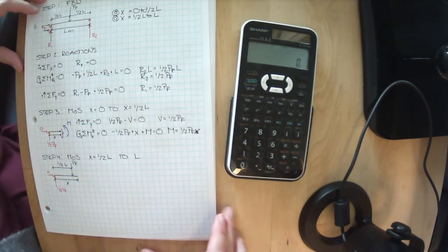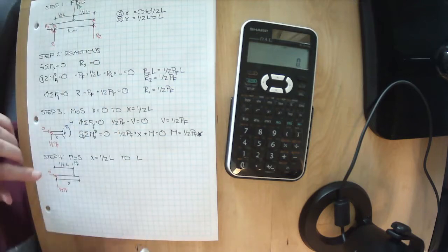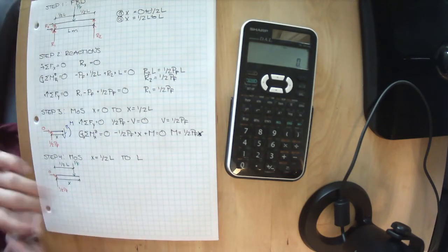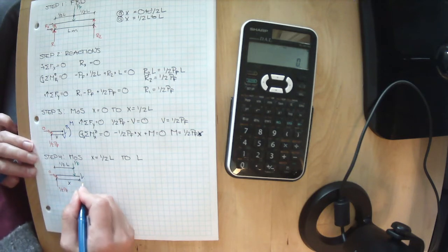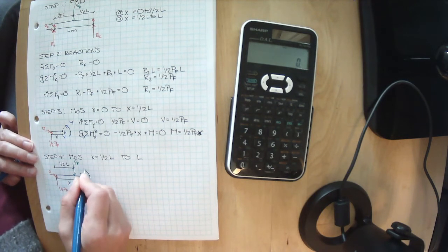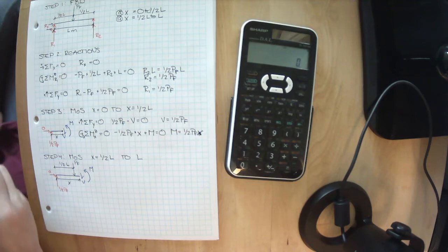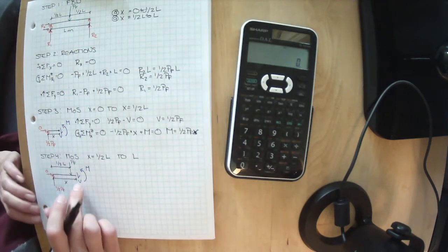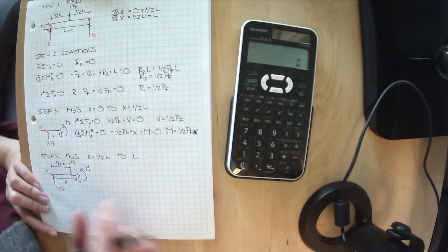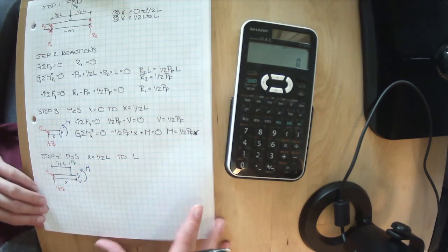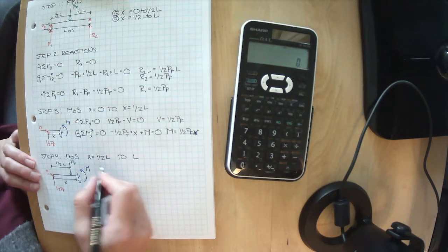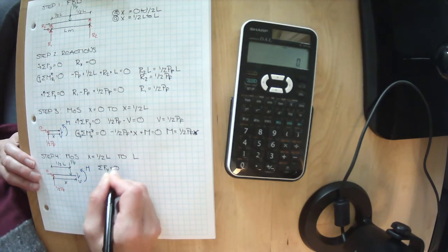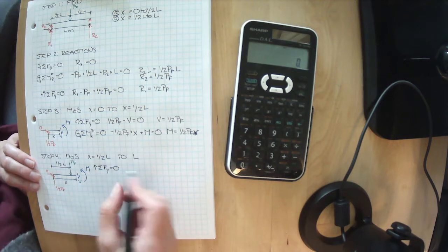Sorry, everyone. Okay. This thing should not be moving in space because it's part of this thing that isn't moving in space. So there must be internal loads that are keeping this thing from flying off into space on us. We don't know what the values are, but we know there must be an internal shear and an internal moment if they have values. So let's sum our forces in the y direction where everything upwards is positive.